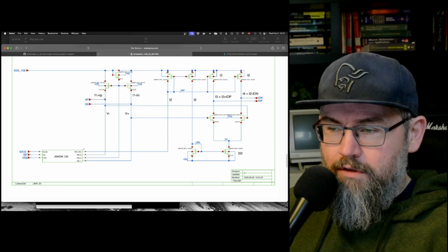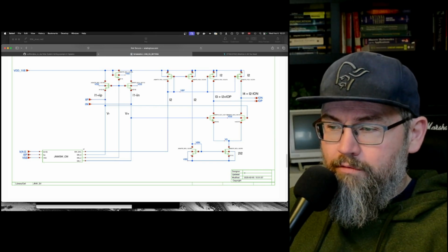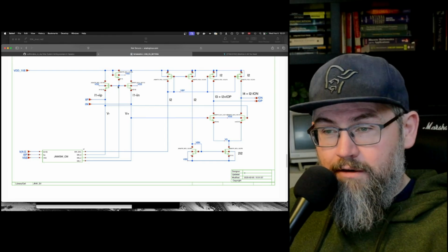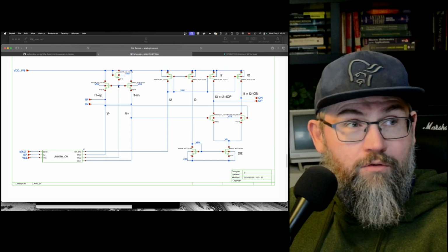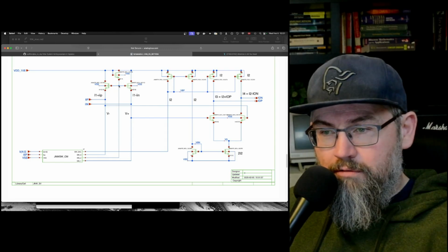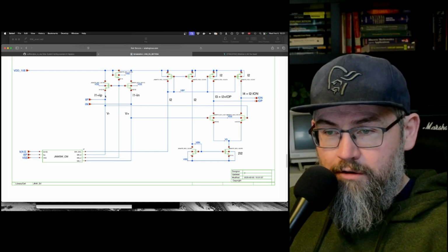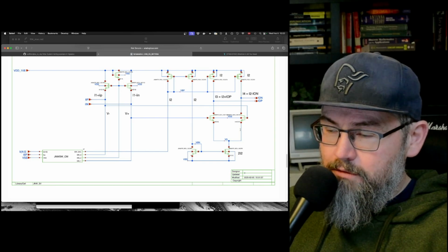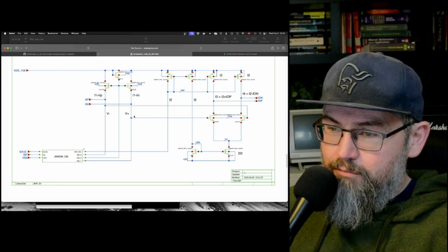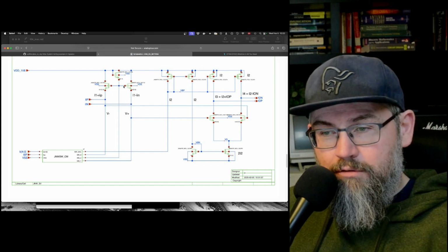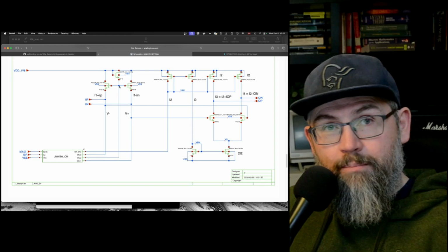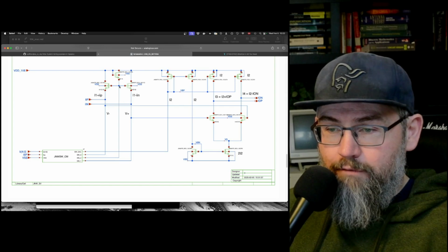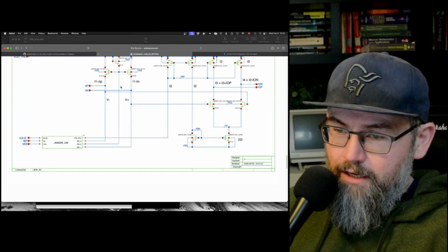Now, the source is going through the gate of two diff pairs. So we can see that if we do a loop again, I can go down from the point here to the source, and then I go down a voltage, I go up the differential pair, and then I go up a source gate voltage again. And now I'm back to where I started. So this is a translinear loop as long as the MOSFETs are biased in weak inversion. So there's an example of that.